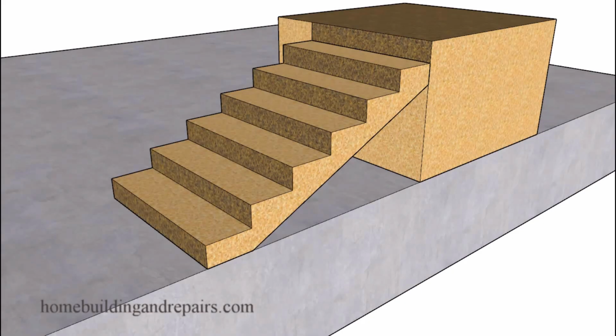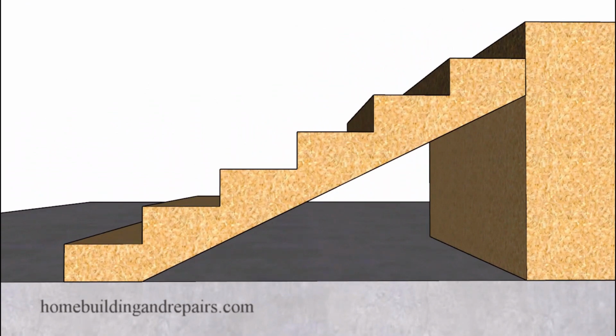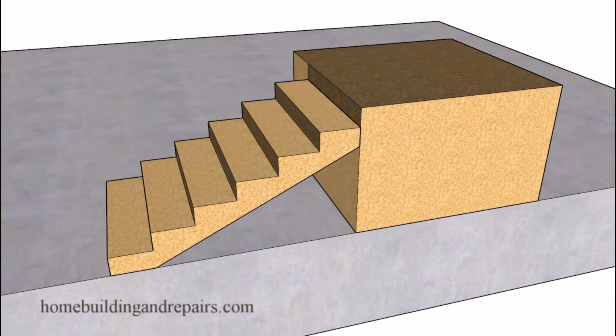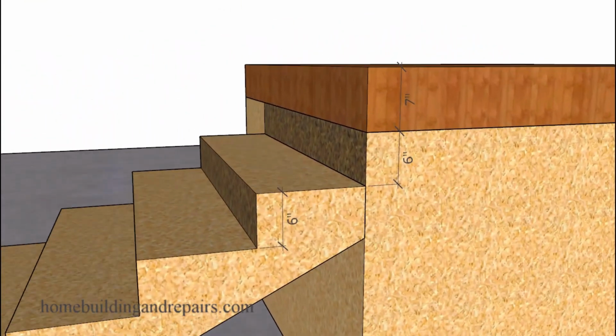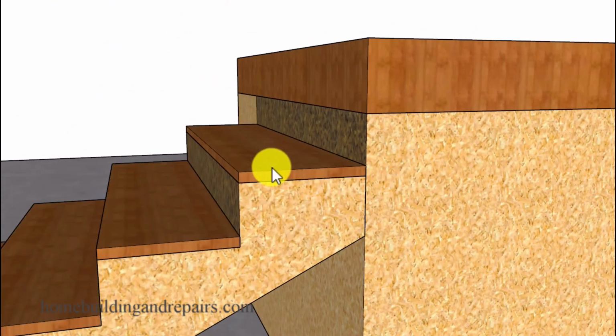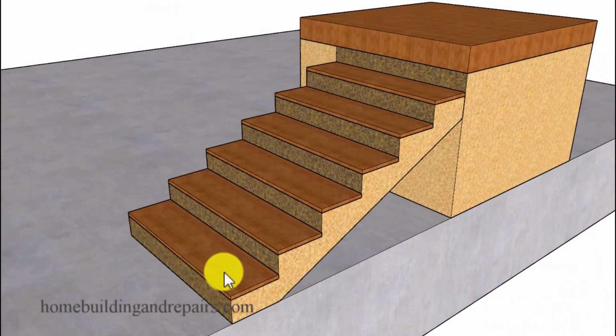Here is another question from one of our viewers. They wanted to know how you could raise the risers on a stairway. And I'm guessing that you would be raising the risers if you raised a deck, porch, landing, or floor. And if you did that, then you could add materials to the top of each step. However, you will not be able to add the same thickness to each step.